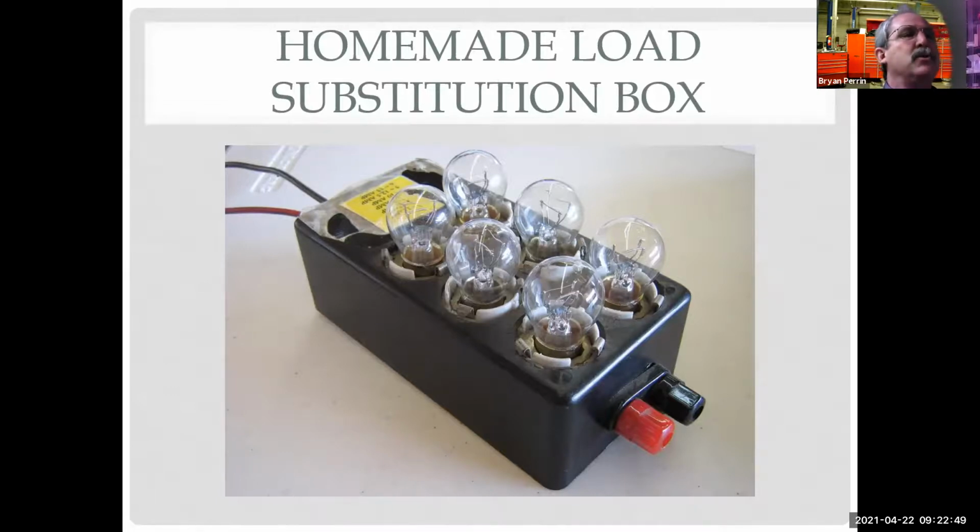The big thing I use this for is if I'm blowing a fuse, I'll take the fuse out that keeps blowing. I'll put this in place of the fuse, and then make the light. If the light bulbs are on, I have a short. Then I just have to make the light bulbs go out to fix the car. That's a lot easier than keep putting fuses in.